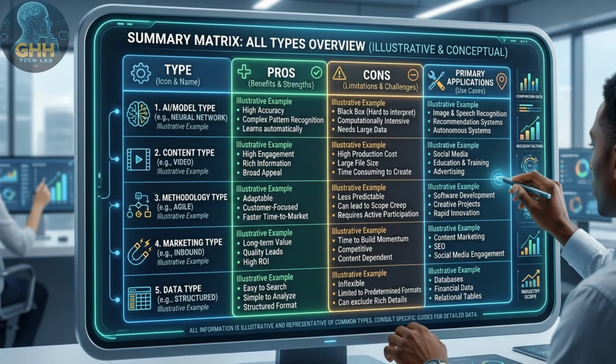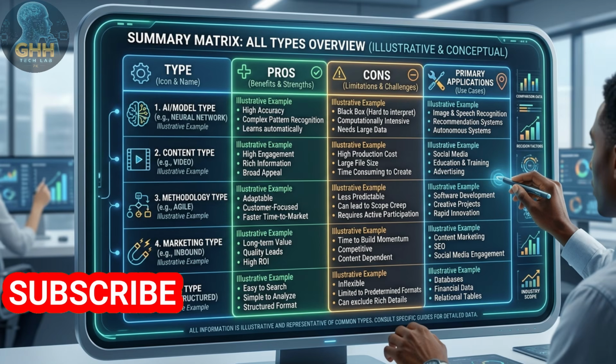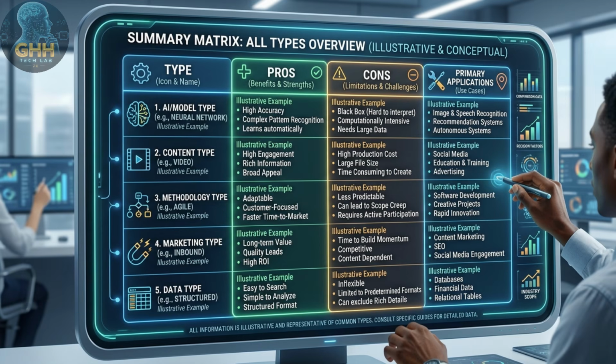Choosing a capacitor isn't just about matching the microfarads. You must balance voltage bias, ESR, temperature stability, and lifespan. Keep this guide handy for your next schematic design, and your hardware will stand the test of time.